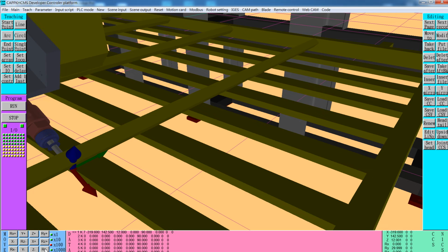We lower the speed and continue to press. Okay, 22 already. We lower the speed. 22.7, 22.6. Okay, right now it's 22.5. This inclined tool position is the welding position. Then we have to recheck. We set the speed to maximum. Recheck, use X minus once, twice, third time.